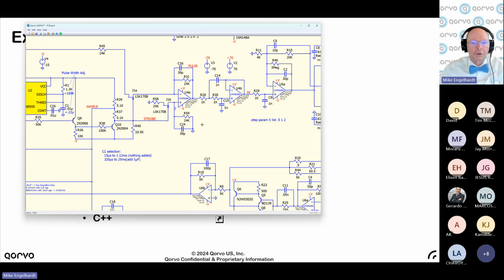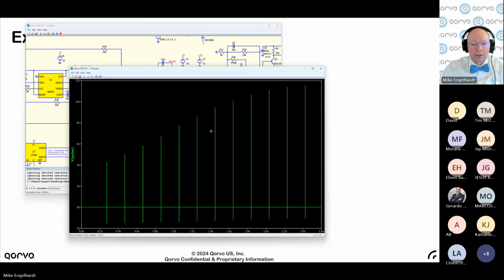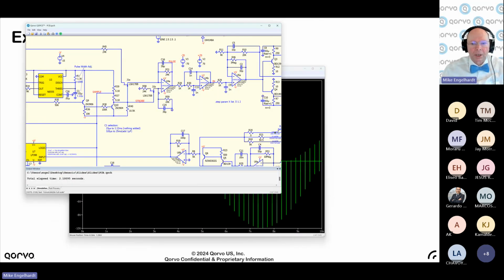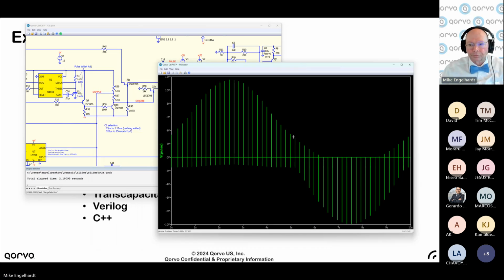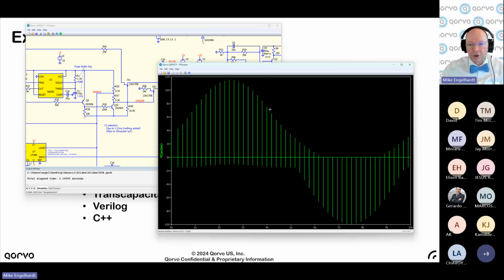The way these things are usually made, these JFET pulsers. And that's the pulse coming out of this thing. Let's zoom in on one of these pulses. Okay, so the problem is that these spikes here is charge injection.